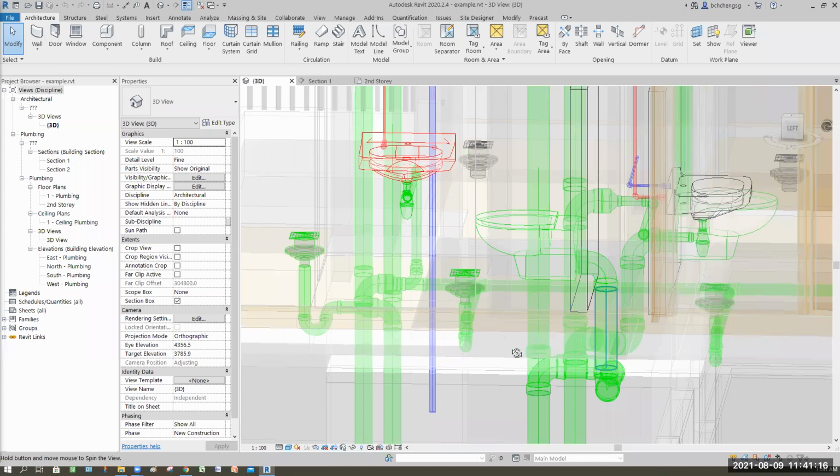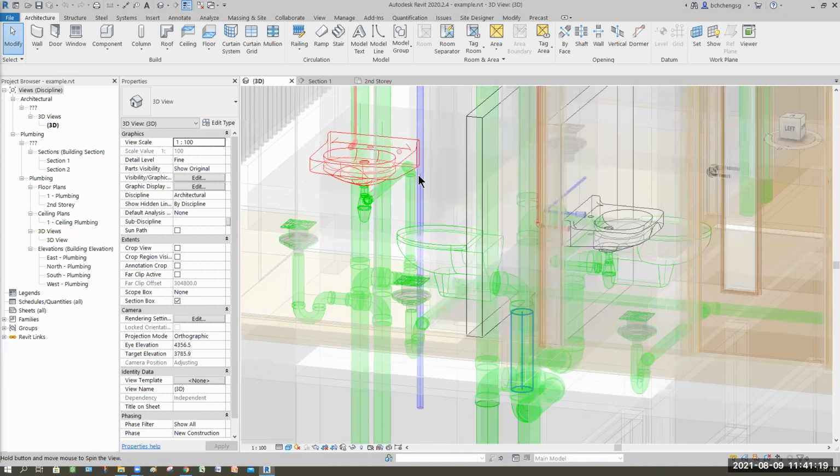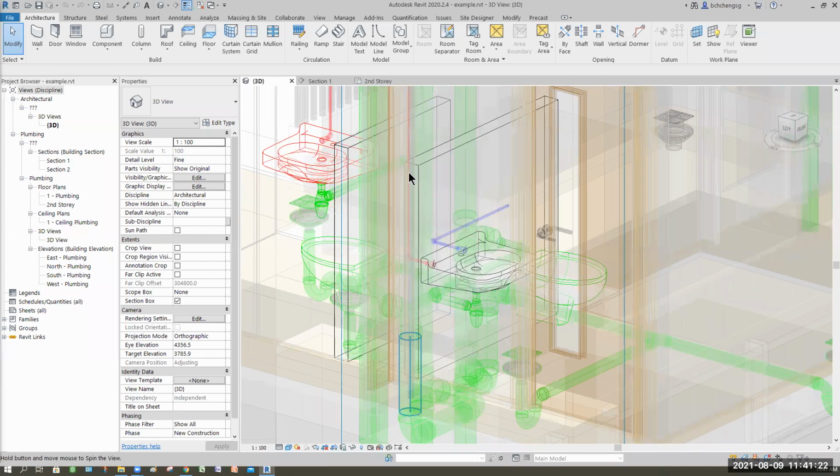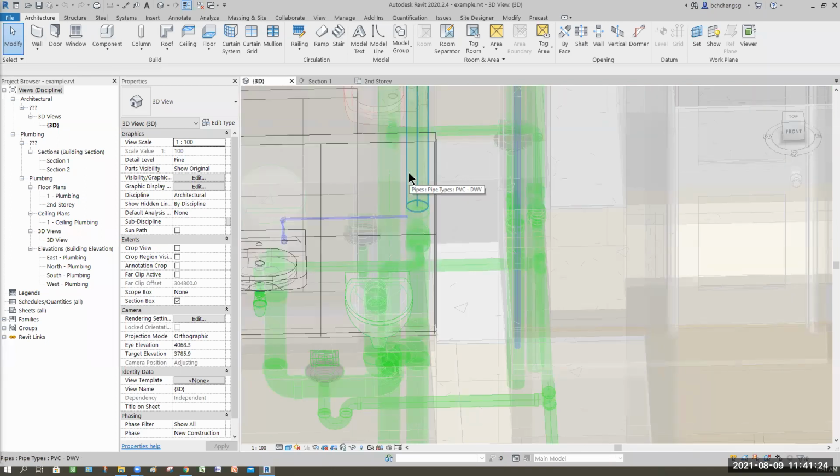But normally, like in this case, when you have two, in between you have some interlink. Why? Exchange of gases. It means the air movement is important. Whatever comes out cannot be a bottleneck. No air, no flow, right? Because of pressure, air release. The waste won't go because it's based on gravity, sanitary. So ventilation is very important. No ventilation, your waste is stuck halfway through. Good luck to you. No joke.